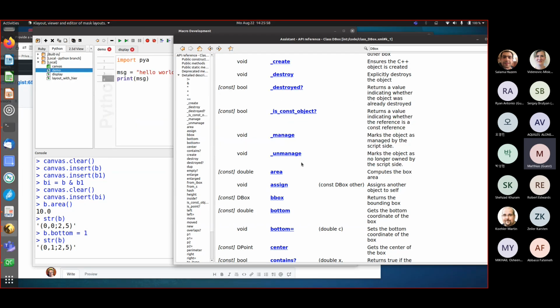In skill, it's different. In skill, you say db create rect, and you give it a layer. So you don't have a standalone box as an object in skill. KLayout has geometrical primitives as objects, and these methods you have here, like the intersection and like bounding box and so on, and we'll come to much higher level operations for the polygon. So they are not available in skill because skill does not have a box object. Well, it does, I'm not sure. At least I don't know. But the function is called db create rectangle, and it takes a layer. Maybe skill has some features to compute, for example, box intersections. But the Pythonic or the object-oriented way of doing that is to define a class that represents a rectangle, and then doing something with this class. So you can modify it, you can work with it.